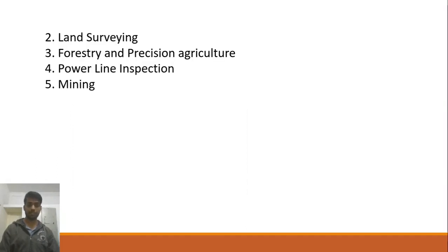The second application is land surveying. Airborne LiDAR scanners can be used to create a digital terrain model or a digital elevation model. Data can be gathered using a drone, aeroplane, or helicopter depending on the size of the surveyed area. A plane can normally acquire swaths of 3-4 kilometers wide in a single flyover. Drones are cheaper, safer, and faster for small terrain surveys where real human beings can't reach due to very critical conditions. Forestry and precision agriculture.